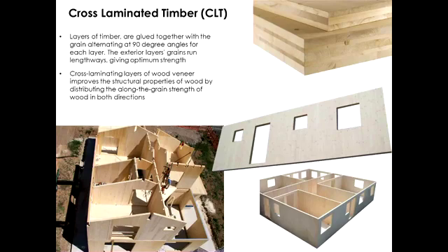I hope that's clear enough. If that's not clear, let me know. But just make sure: odd number of layers. When you look at it from both sides, the grain has to run in the same direction.